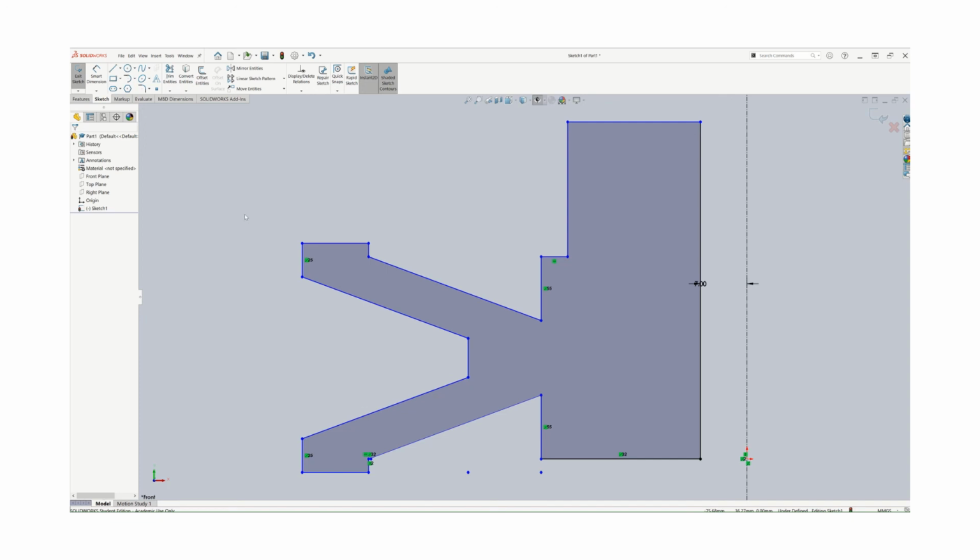But before we leave, I showed you before how to trim, how to do fillet in 3D, but we could do this fillet in 3D. In this case, the radius is 3 millimeters. So choose fillet and choose that the fillet radius is 3 millimeters, between these two, and between that, and between these line segments, and also one more from here to there, so that I could have this full fillet. And then I'm done with the profile, so I will exit sketch now.